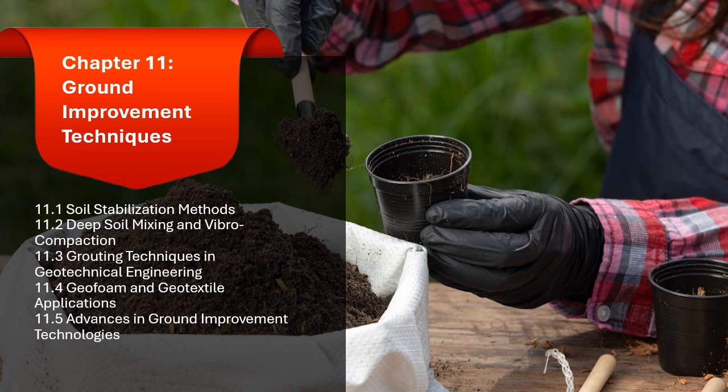11.3.1.3 Jet grouting. Jet grouting uses high-pressure grout jets to erode the soil and mix it with the grout, creating solidified soil cement columns. The technique is used to treat deep soils and is effective in both cohesive and non-cohesive soils.